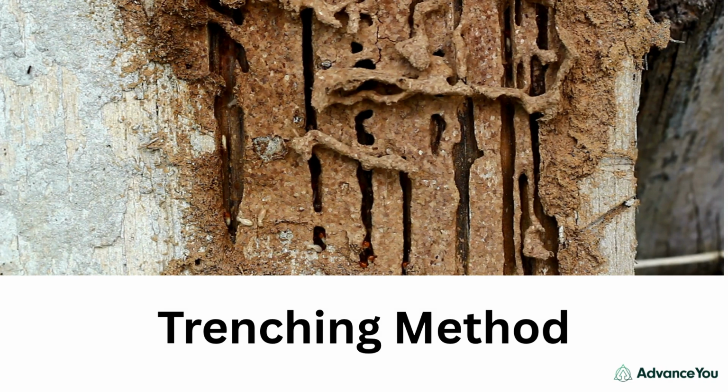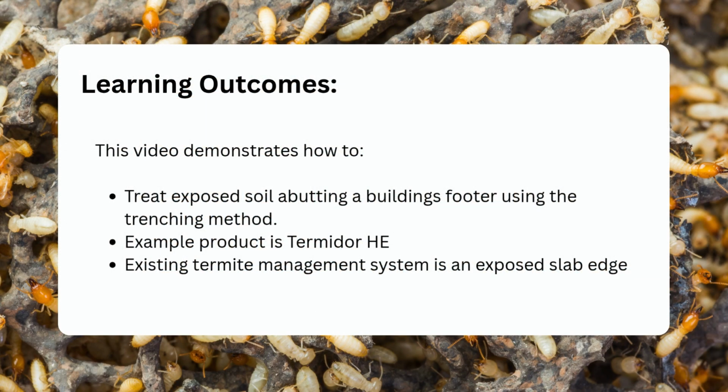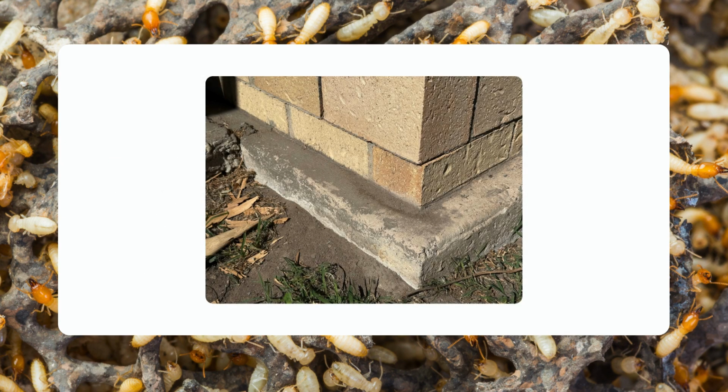The video will demonstrate how to treat exposed soil abutting a building's footer using the trenching method. Example product used in this video will be Termidor HE. The building has an exposed slab edge as its current termite management system.